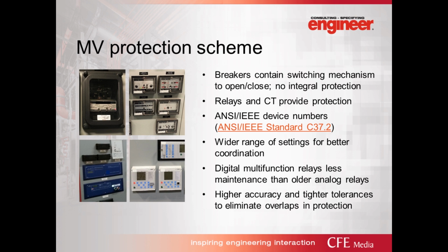The digital multifunction relays have less maintenance than the old analog relays, and they have a much higher accuracy and tighter tolerance, so that eliminates a lot of the overlapping in the protection schemes that you would see at the low voltage breakers.